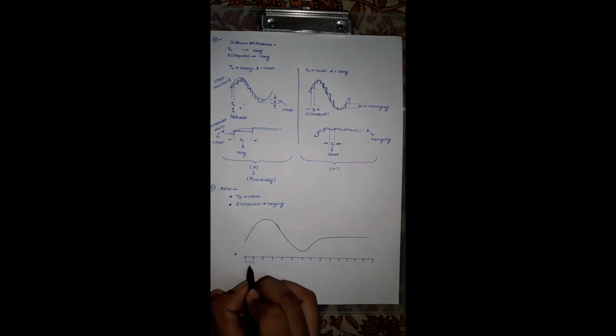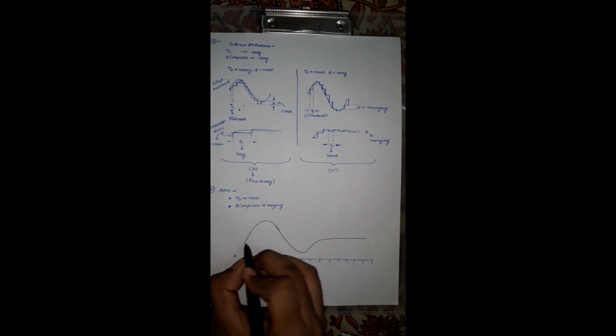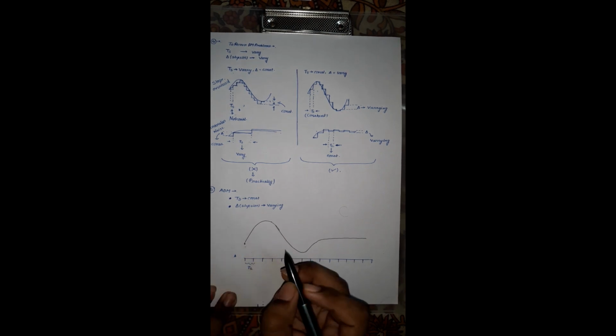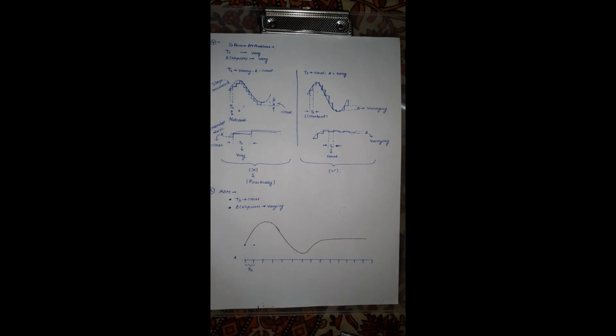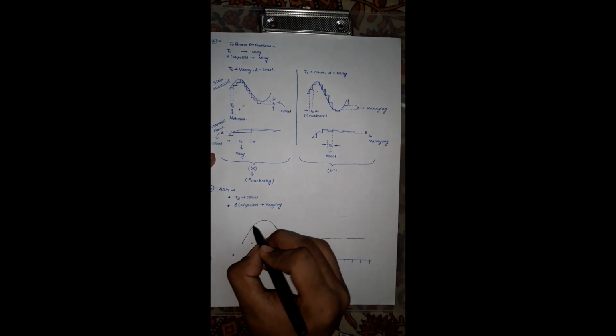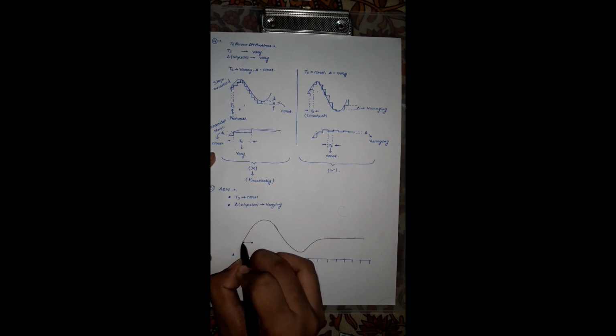This is fixed. So what it is doing actually is varying the step size. Suppose at the second sampling time, at t equal to 1, it is watching that the amplitude of the signal has been varied too much. At that time it will increase its step size.